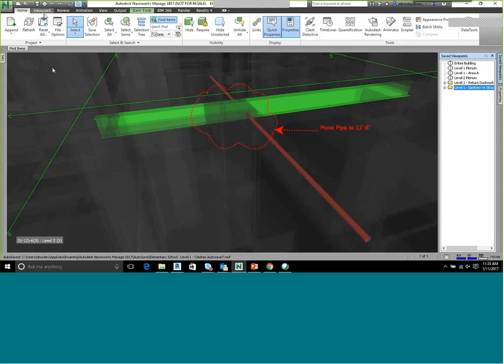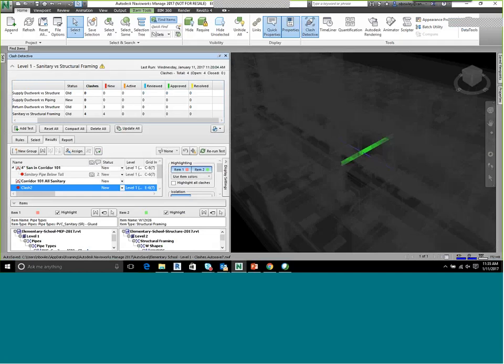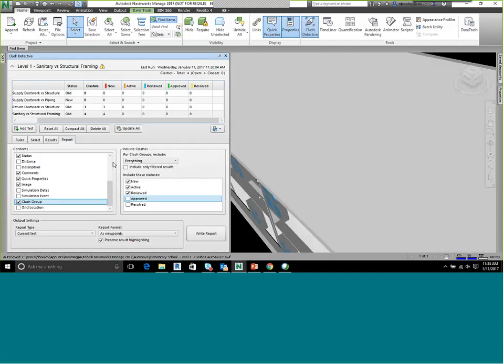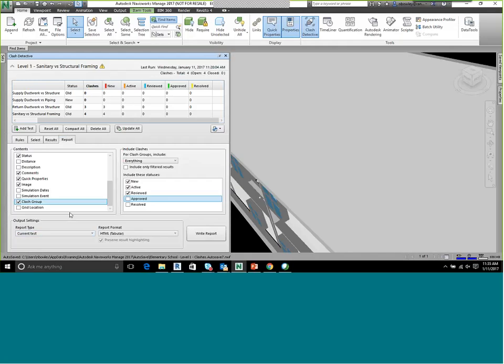All right, let's go back to the Clash Report wizard and let's do a real HTML export. I have a report. That's fine. And so what I'm going to do is choose HTML Tabular this time. Not HTML, HTML Tabular. It's a big difference, so always remember to use the tabular format. It set the current test, and my current test is my sanitary report.